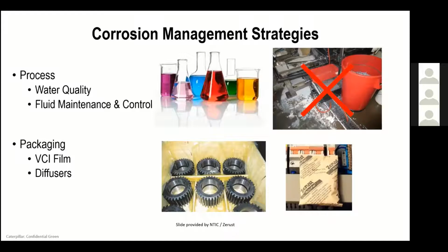Anybody in the manufacturing world will find it gets pretty costly, and they'll have a number of issues with corrosion if they don't have a good fluid maintenance and control program. And that's not only on the metalworking side of things. After you machine the metal, you want to make sure that you clean it, and clean away the metal fines and other material on that component, because that surface area could promote early corrosion.